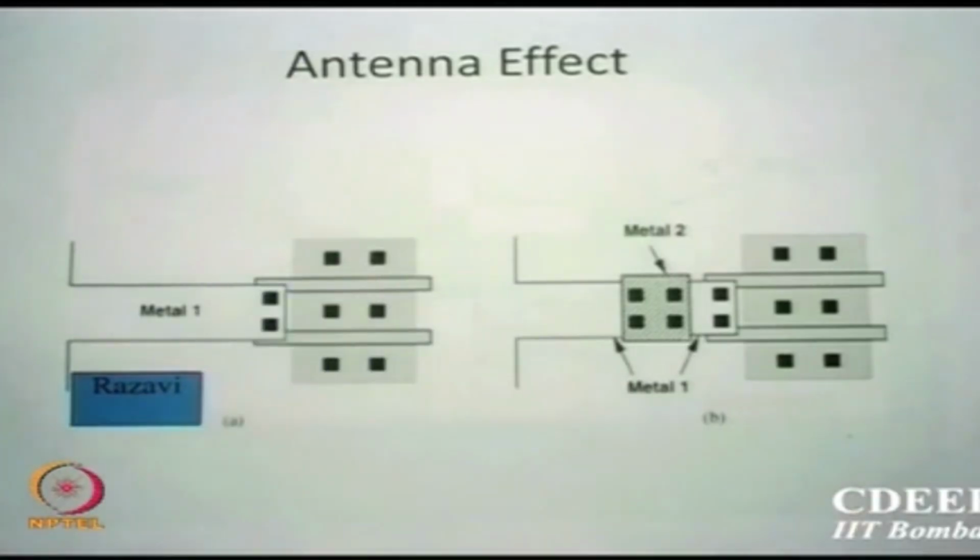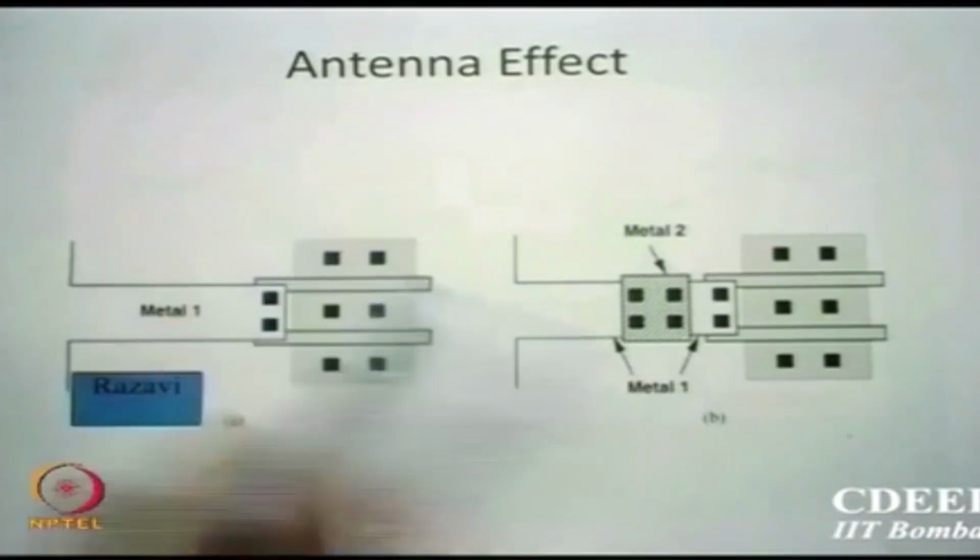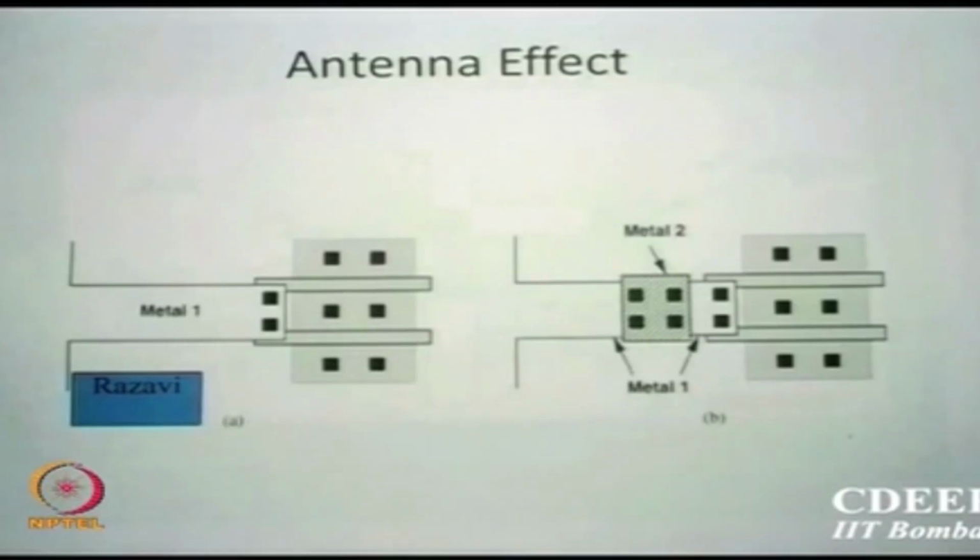So the drain of the two is the same, but it is only a matter of decision, because they are symmetric. This we also count as source and drain. So you connect the source and drain in between, or call it the drain, or both together, whichever way you feel like, as long as the devices are symmetric. There are other devices called asymmetric. Devices like LDDs and others do not have source the same as drain, so don't connect like that.